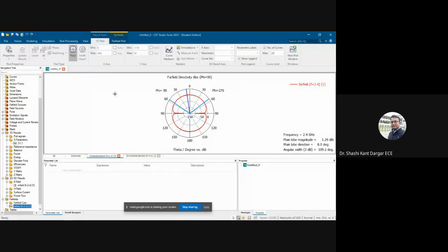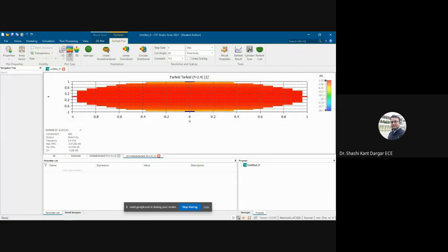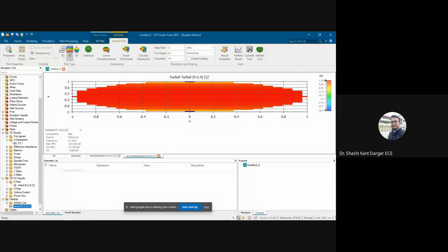So you have to get it for 3. You can see on the right side written far field 2.4 gigahertz. So in the three cases which you will generate, it will be far field for 1.4, 2.4 and 3.4. I want this for three different frequencies. And similarly, in the beginning of the project, when you select the frequency range, take the frequency range larger, from 1 to 5 gigahertz. In between that, we want to check how our antenna is working. Is that okay? Thank you, thank you.